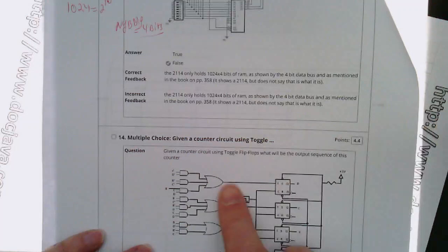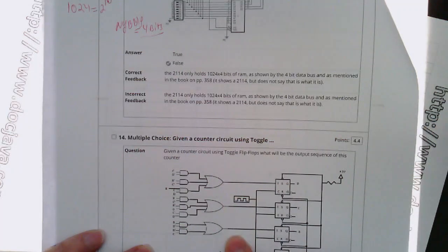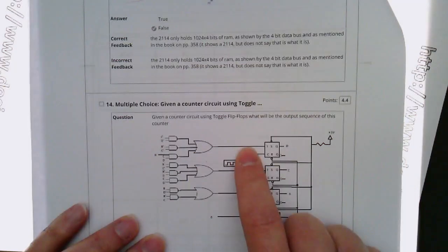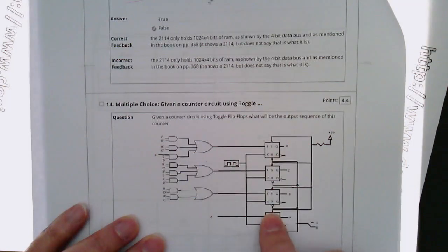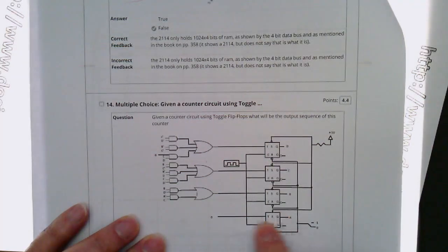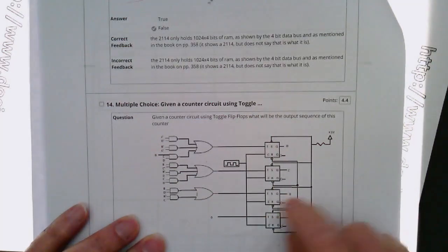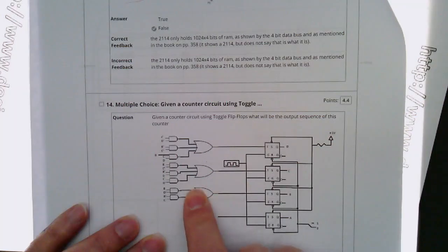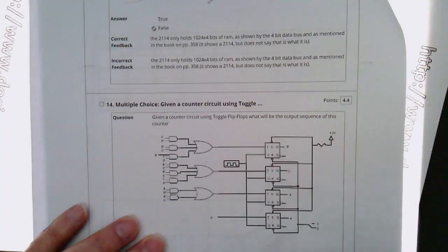So, sorry about that. But what you're going to do, and here's the approach, right? You're going to write down the equation for each one of the inputs, including this one down here at the bottom, and then you're going to write out what the next state will be after you've written out the present state. And this is A, B, C, and D, so you'll write this out. And in fact, this is 0, so you can eliminate it and just do B, C, D. And when you look at the inputs, you should be able to figure out what the equations are by inspection. And once you've got that, you should be able to write out what the toggle flip-flop inputs are, and that'll give you the next state.